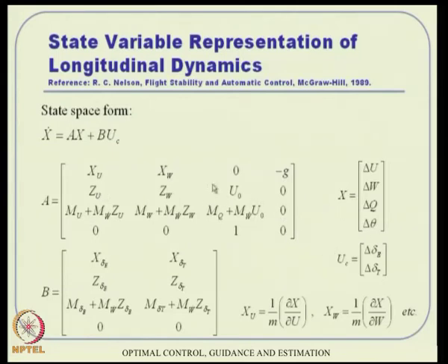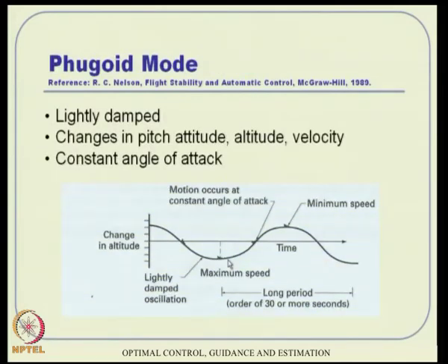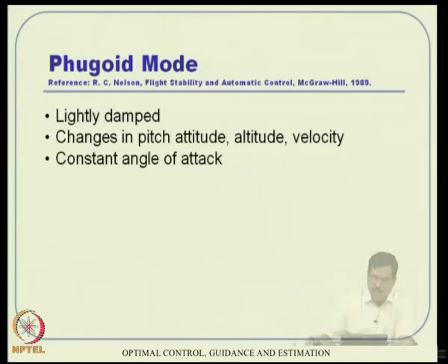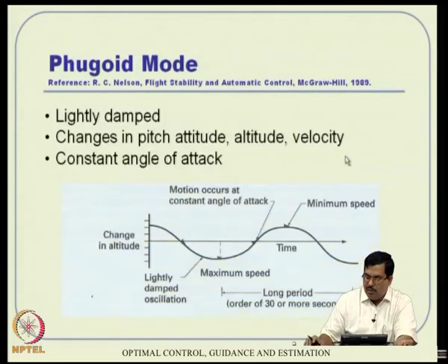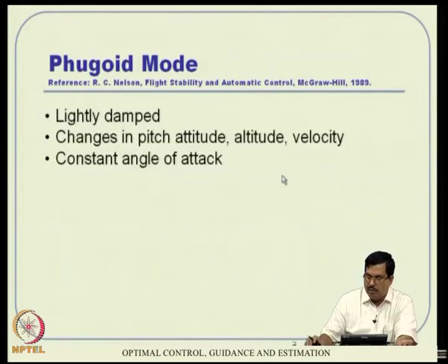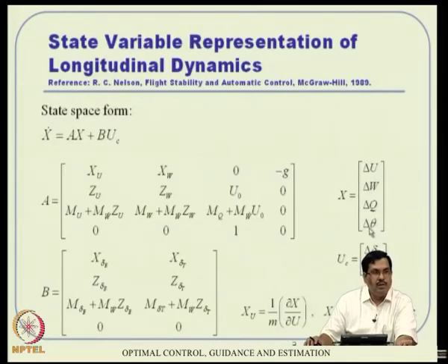So in flight dynamics, suppose somebody gives us this A and B matrix numbers, these numbers essentially mean these quantities. That means they are coming from there. And that's the thing, and there are nice consequences. Now, I can further divide this 4 by 4 into two 2 by 2 systems. One time I will talk about delta u and delta theta together. Other time I will consider delta w and delta q together. That's what it turns out.